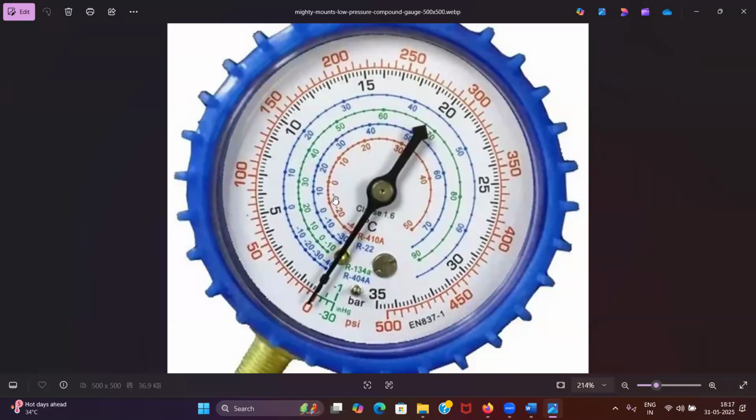Agreed? Yes, sir. These temperatures are written for different refrigerants. Look here for reference: R410A, R22, R134A, R404A, R407, okay? We have different ones. Right now we are using 134A, for refrigerator. 404 is also being used, 134 is also being used, depending upon your company, okay? R22 is not used nowadays. Before we were using R22. R22 is in your split ACs that are installed at home. Sir, it is R32, right, sir?